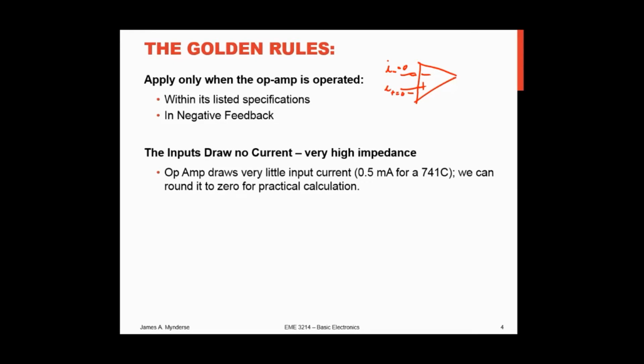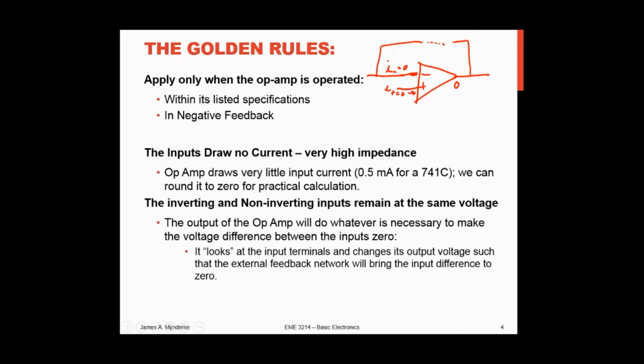So I have no current going into this device here, okay? Output, and we're going to have something up here. There's always this negative feedback. So by assuming that there is no current going into the device itself, it really simplifies our calculations or our analysis.